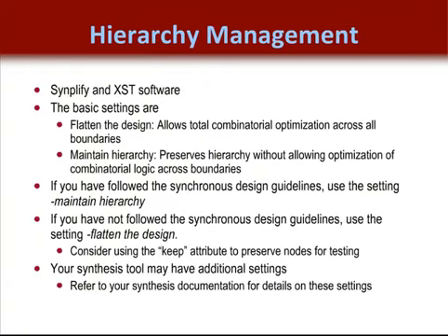Xilinx recommends that hierarchical optimization be considered carefully. Now that is a standard synthesis option that allows users to optimize combinatorial logic across a hierarchical boundary. Now we recommend that this hierarchical optimization be turned off. This is because synthesis tools will change node names and change the logic optimization on nodes that users will often want to simulate, probe, debug, or analyze in some way. Allowing this optimization will sometimes make debugging nodes on a hierarchical boundary much more difficult.